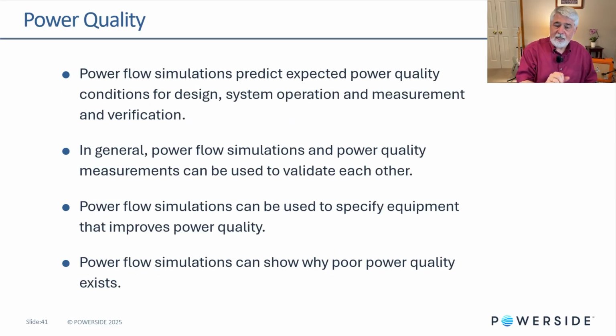Power flow simulations have the ability to predict power quality conditions for design, for what you want to mitigate with, system operation, how is it going to operate, and then finally, measurements can be brought in for measurement and verification. So again, they're working as a pair together. In general, I would say power flow simulations and power quality measurements can be used to validate each other.